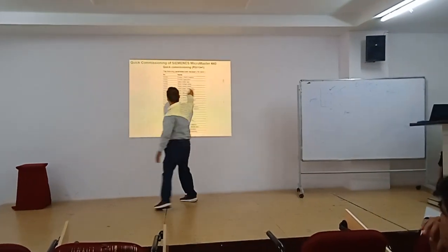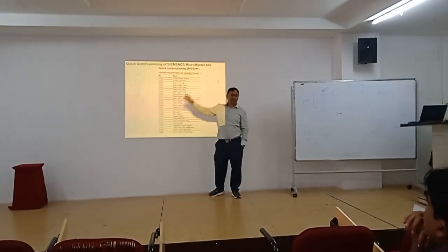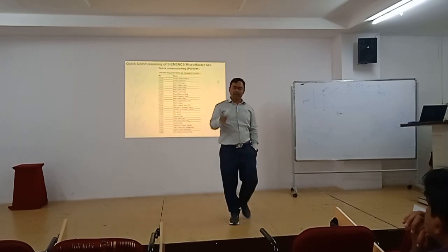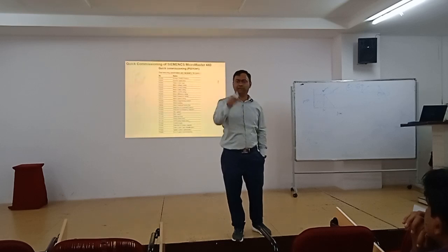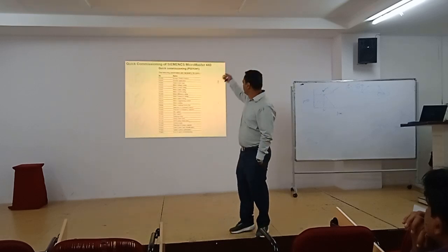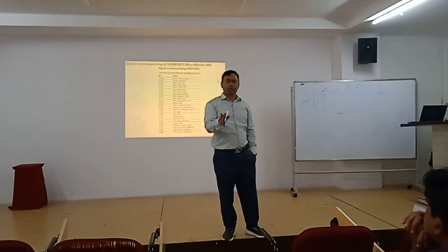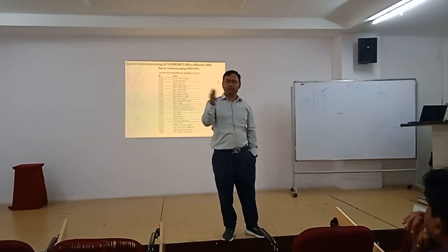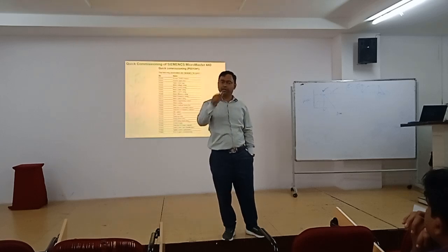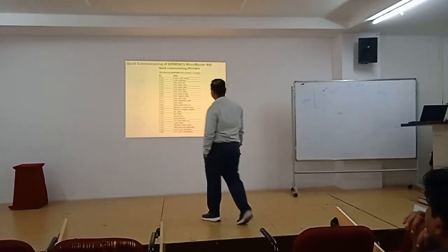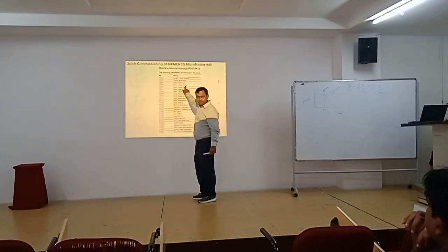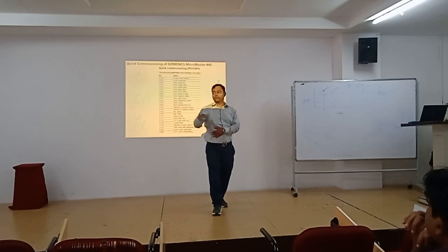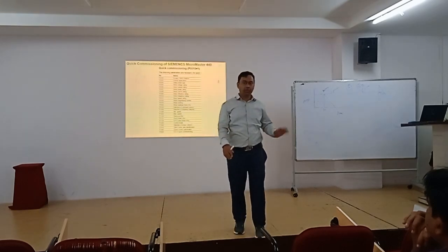For example, anyone can understand parameter P1001, whether it's European or American. It just defines the frequency. If it's European, then 50 Hz; American, then 60 Hz. You select 50 Hz. Then parameter 205 is the application: constant speed, variable speed, constant torque, and you select accordingly. Then mainly the motor power rating, motor current rating, and motor voltage rating. Whatever the motor rating is on the nameplate, you enter that.